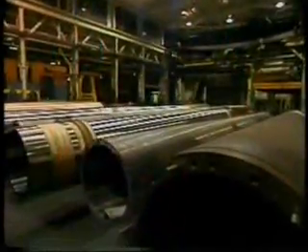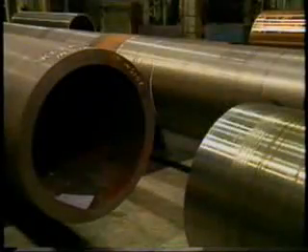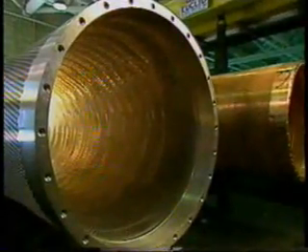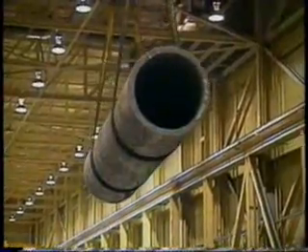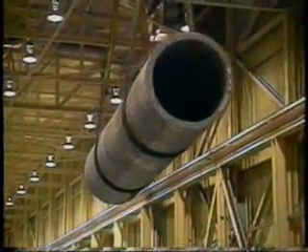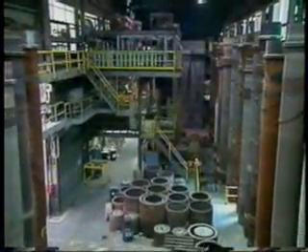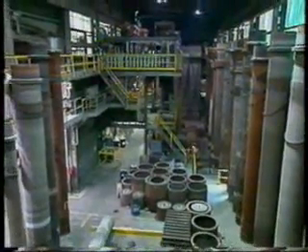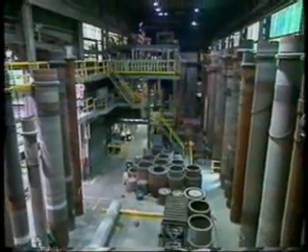In true centrifugal casting, metal is poured into a mold rotated in the horizontal or vertical plane about its central axis. This method is used to produce large diameter tube, bimetal tube, and rolls of virtually any wall thickness and length. Outside diameter and length are controlled by the mold. Inside diameter is controlled by the amount of metal poured.